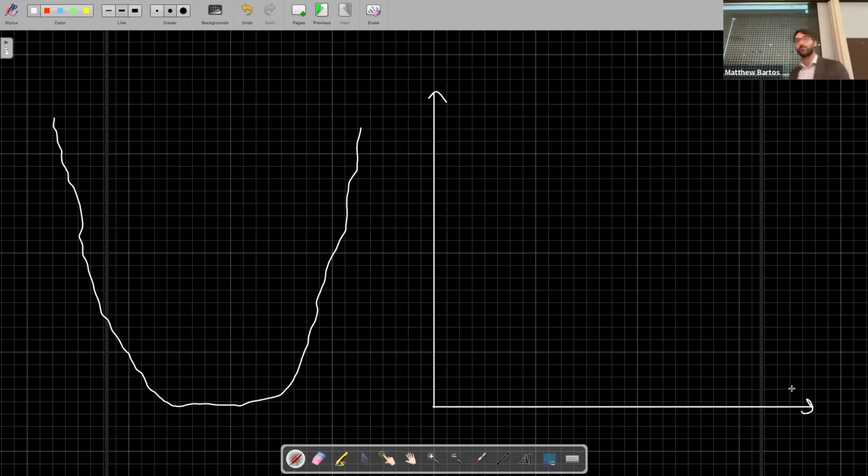So in this channel, for a given discharge, we can have flow traveling at different depths. So for all of the lines I'm about to draw, all of these lines are operating at the same discharge, just at different depths. So as the depth decreases for a given discharge, the velocity will increase because they all have the same discharge.